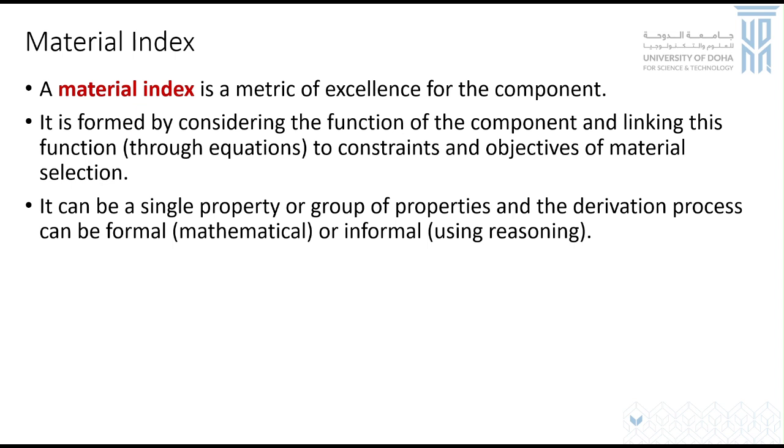It is a metric of excellence for your component, meaning that you can use that in combination with your constraints and objectives to define the correct material for that application, right? Normally, this material index can either be a single property, or it can be a combination of properties.